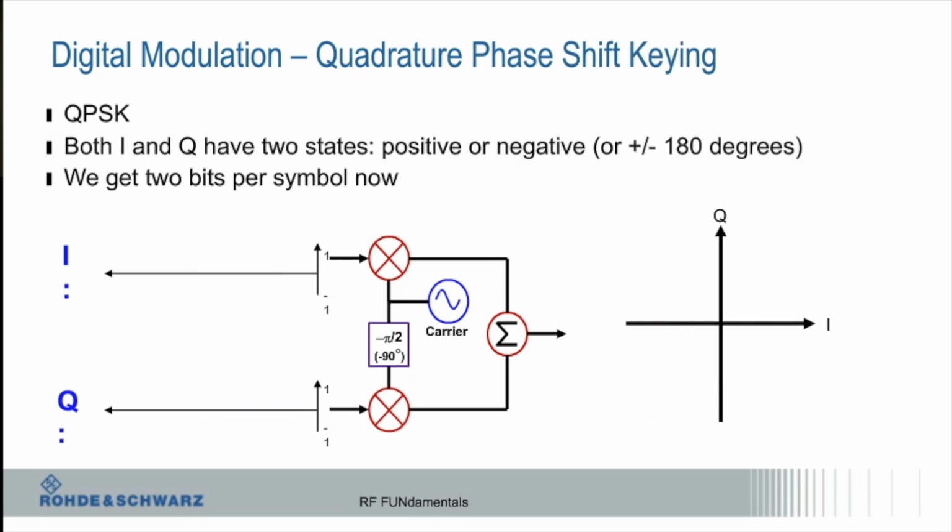So then I go to QPSK. Now I'm going to have information on both lines. I put in a 1 in both of them, and I'm going to go up here. And realize that while on this diagram I'm showing the point here for 1, 1, it isn't necessarily 1, 1 here. You define what this map is. You get to say 1, 1 means I'm here, or 1, 1 means I'm here, or here, whatever. You define that in your map diagram. So if that's 1, 1, then that would be 0, 0 down there. And that's 1, 0, 1.